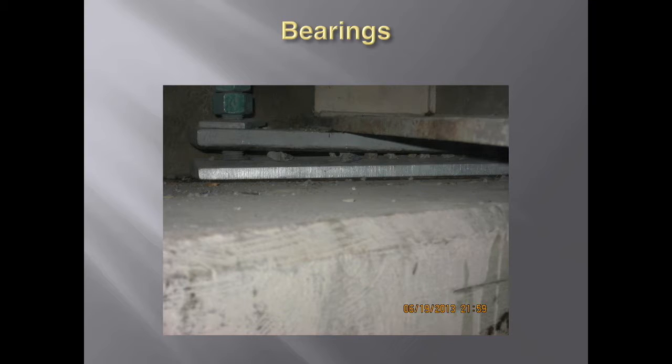They formed it and started pouring, and one of us happened to go down and notice that nobody had checked the bearings, and you can see the gravel in between the rockers here. They ended up jacking everything up, stopping what they were doing and cleaning these bearings out. It was a 5-minute check. If somebody would have checked the bearings before they started placement, we wouldn't have had this issue. It would have been real quick. They could have lifted them up and blown them out with probably compressed air and got everything out of them.